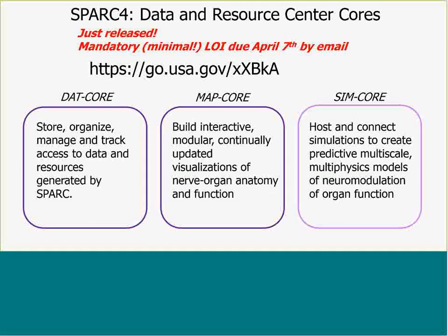To add to that, a couple of examples where the use of the device is evaluated. For example, if you have a stimulator with a lead that stays in the body, it turns out that the leads are not perfectly sealed. So over time, liquid goes into the lead itself. That liquid changes the electrical properties of the lead. So the evaluation of RF safety needs to take into account the amount of liquid that goes into the lead over time. And this is currently done in the analysis of the safety.